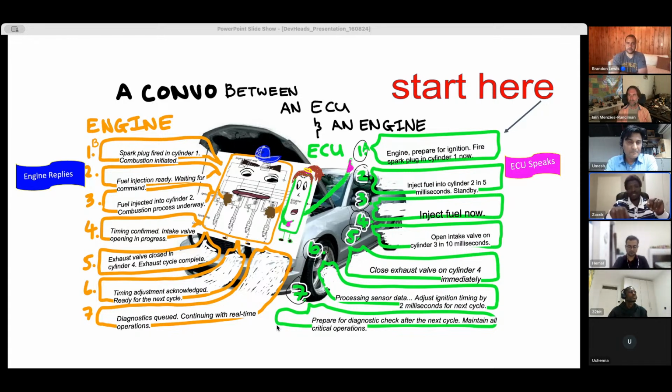So it lets the logging thread take over and finish logging so that it can take over. But in that time, because the logging thread is a very low priority, let's say a priority of 0 and the injection is a priority of 5, maybe some priority 3 thing happens.